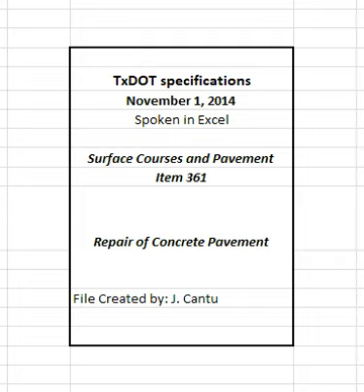2.2.2 Base material. Furnish cold mix asphaltic materials for replacement base material when shown on the plans. The engineer may waive quality control, QC, tests for base material. 2.2.3 Asphalt concrete. Furnish asphalt concrete material for overlay and asphalt shoulder repair as shown on the plans. The engineer may waive QC tests for this material.